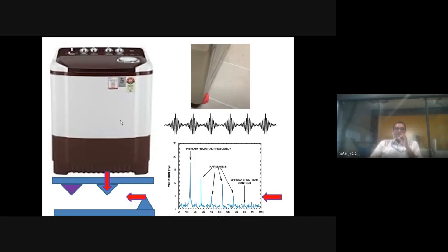So what we came to conclude in this particular slide is, by redistributing the system, you can reduce vibration. By providing isolators, you can attenuate vibration. The other thing is resonance, which happens in the harmonics, and it is the coincidence of the operating frequency and the natural frequency of the system. Different modes will be there, harmonics will be there. To avoid that, we have to either avoid the coincidence, or reduce the time of interaction between the harmonics and the operating frequency of the system.